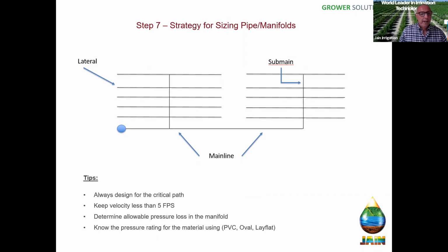So Perry, on these manifolds and your filter systems, how do you feel about injecting fertilizer downstream of the filter? You know, I've never won that argument so far. Farmers love to inject downstream of the filters because they're afraid to flush the chemical out, or they're afraid that the filter's somehow going to keep some of the fertilizer back.